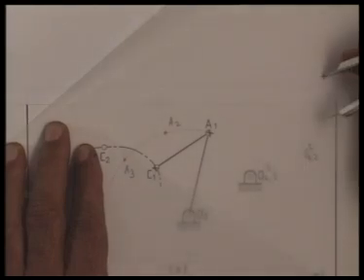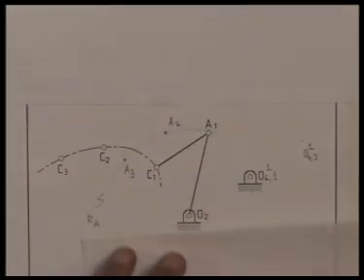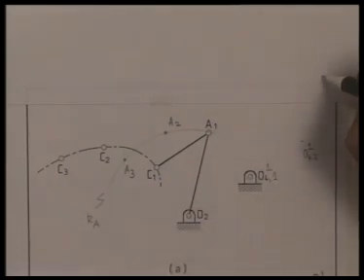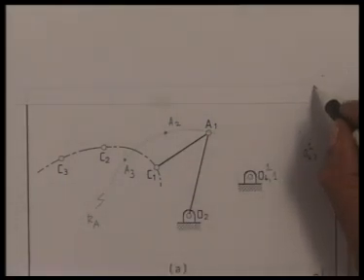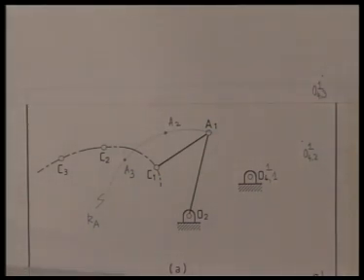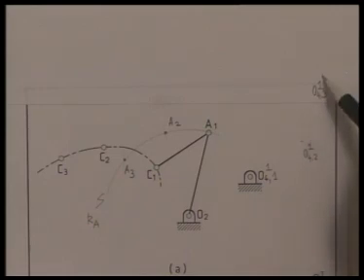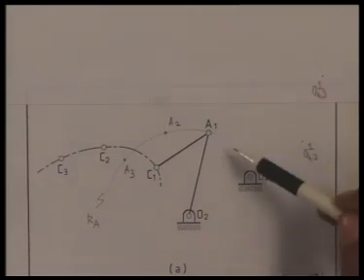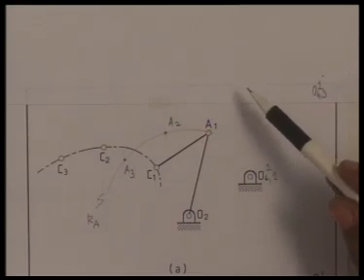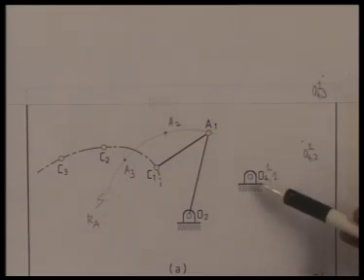So I mark this point on my drawing sheet, and this I call O4 3 1. So if the coupler is held fixed corresponding to these two relative movements or these three configurations, the location of O4 is here, here and here. If the coupler is held fixed at its first configuration, that is the point B does not move, it remains in B1, and O4 moves in a circle with O4B as the radius.